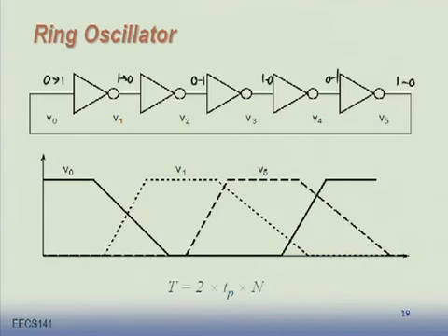Evaluate the characteristic of a new process. Whenever they publish that they've developed this kind of process, they'll publish this as well. They'll lay out the ring oscillator, and from the ring oscillator they'll get an average propagation delay for an inverter. It's easy. How long does it take for this zero to loop around?